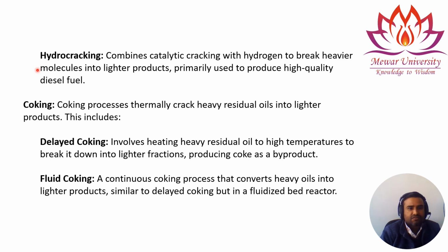And next is fluid coking. It is a continuous coking process that converts heavy oil into lighter products, similar to delayed coking but in a fluidized bed reactor. So this reaction is similar to delayed coking, but it happens in the fluidized bed reactor, and delayed coking does not happen in the fluidized bed reactor.